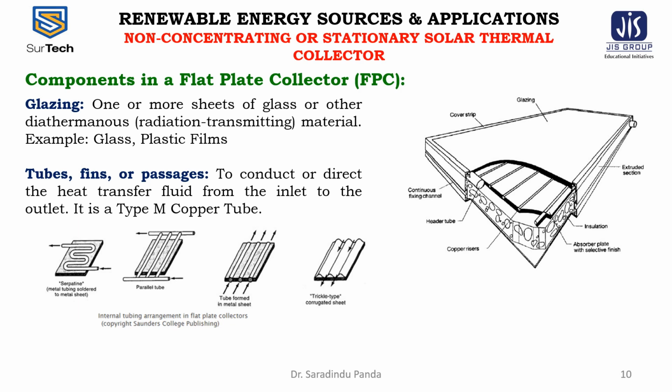The glazing should admit as much solar irradiation as possible and reduce the upward loss of heat as much as possible. Although glass is virtually opaque to the long wave radiation emitted by the collector plates, absorption of that radiation causes an increase in the glass temperature and a loss of heat to the surrounding atmosphere by radiation and convection.